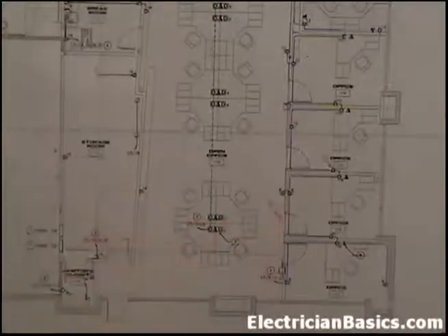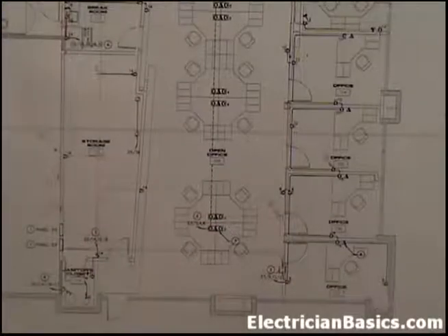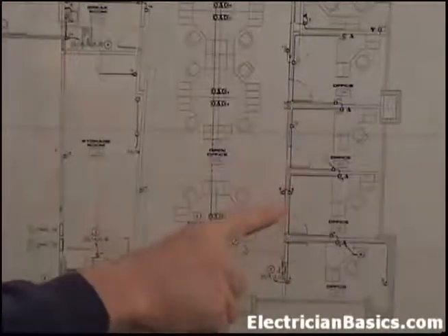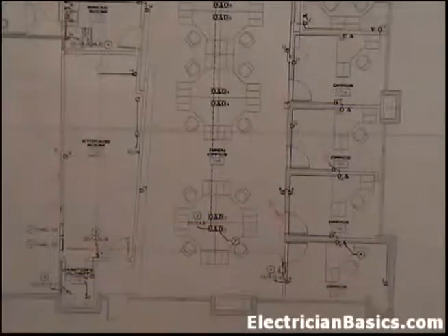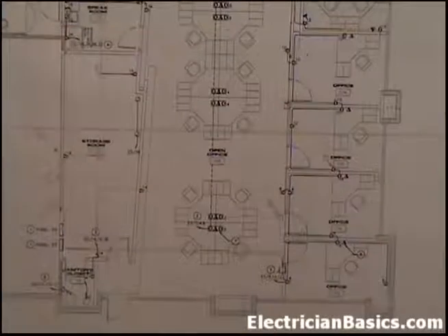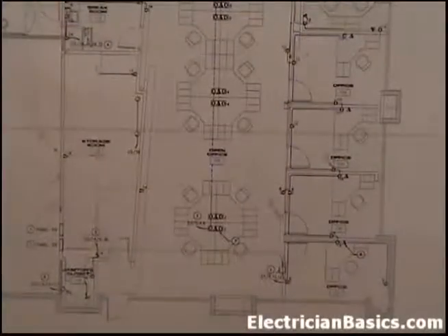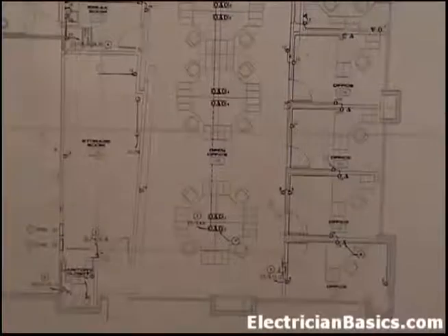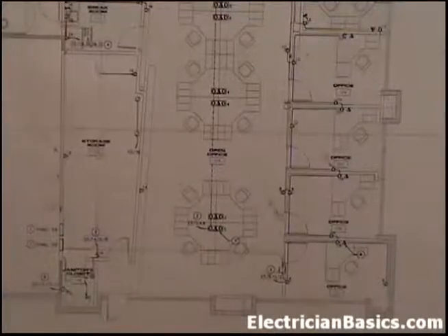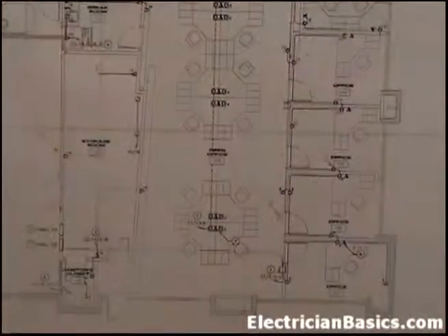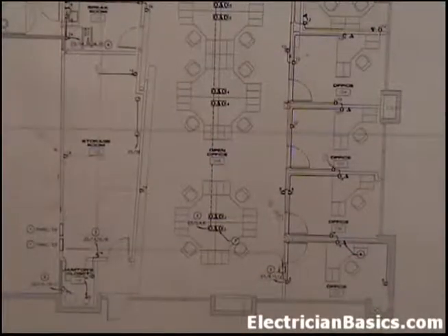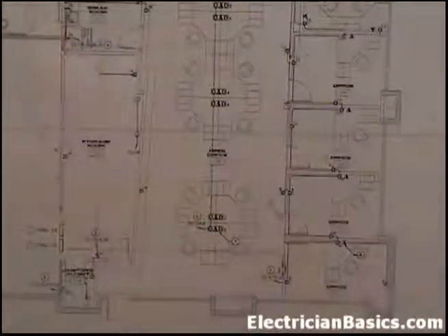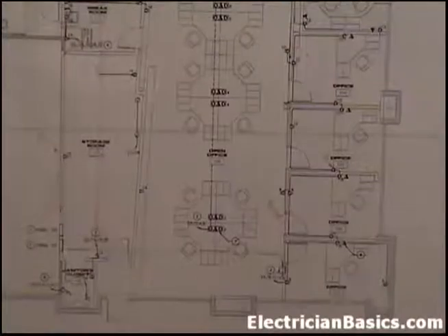Now, even though this junction box isn't drawn exactly on the wall, that's okay, and it may not be exactly over the door. What you want to do, though, is make sure you get this, let's say within one ceiling tile, like a 2x4 ceiling tile, get it really close. I mean, be as precise and as accurate as you can. But the main thing is that if somebody opens the ceiling tile, then they look at the junction box and they can read what's on the cover, then you've done your job well if they can do that and most of the time hit it with that first tile. Okay, so that's what we showed here.